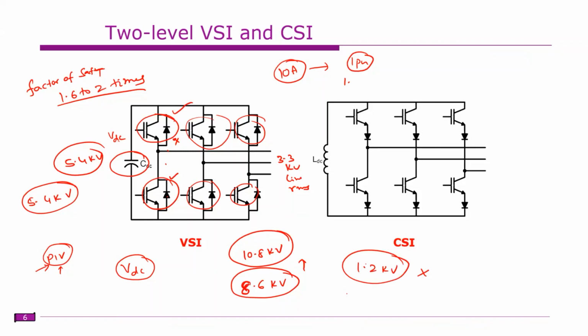It does not come with an over voltage rating. We have a transient voltage rating, which may be for some microsecond or millisecond duration. But for sustained over voltage, it cannot withstand. If the over voltage is there for a longer duration, maybe 1, 2, or 3 seconds, the device may not accept that and may be damaged, and the damage is permanent.